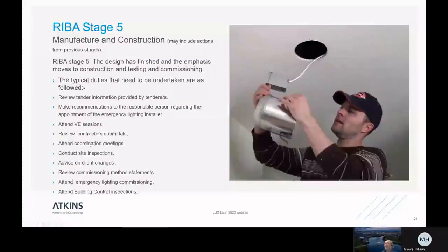There may well be movements or whatever of the emergency lighting required through additional coordination or changes by the architect or other members of the team that require changes to the emergency lighting. We shouldn't think that these are there. We should look and do regular site inspections to see that the design is moving in the way that we expect.